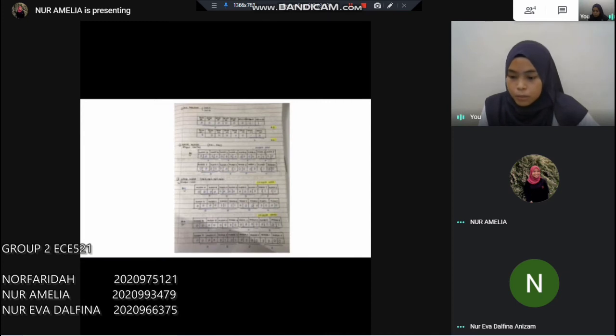Next, we will need to find the value of GPIOA MODER. So we are going to put logic high on the pins that we use. Therefore, we have pin number 1 and pin number 4. And by giving a value of 1 into the MODER, we will have a value of 0x0000030C.